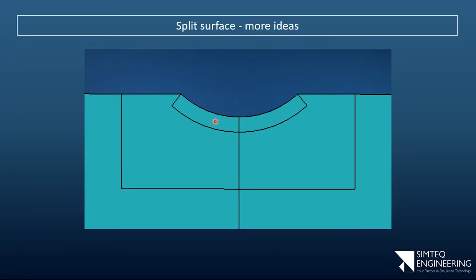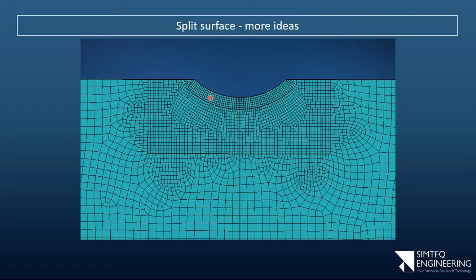And if I look at these surfaces, they're pretty simple iso-meshable surfaces, which means I can get exceptionally nice elements in this region and then transition to slightly worse. So if I mesh this, you can see there's a really great set of elements over there. The region that's got worse elements is moved a bit deeper, but even then it's 2 of them there, but then a lot of really nice elements again. There's some bad ones, and there we start seeing slightly worse ones.